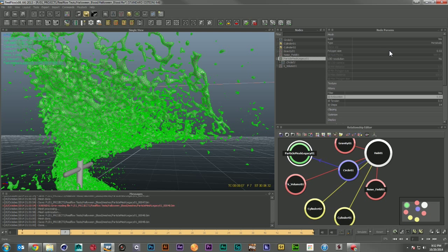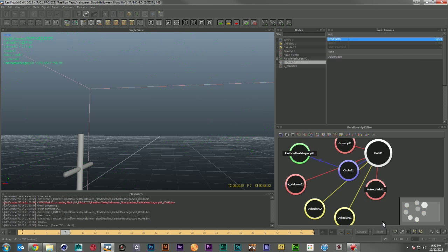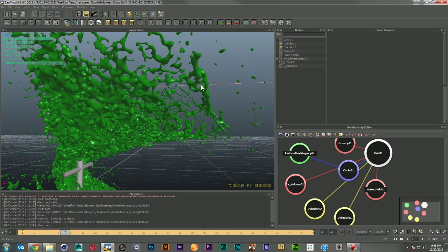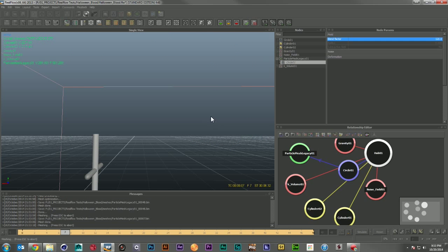So what I need to do is come back, and I want to go ahead, increase my blend factor a little bit. And the blend factor and the radius are kind of a yin and yang. You can push them in opposite directions or in the same direction to kind of help achieve the look you're looking for. So I'm going to go ahead, click on my build again. And see if we can get a little more cohesion here. We're starting to see it. That's a little better. I'm going to maybe go up to 120, build it again.